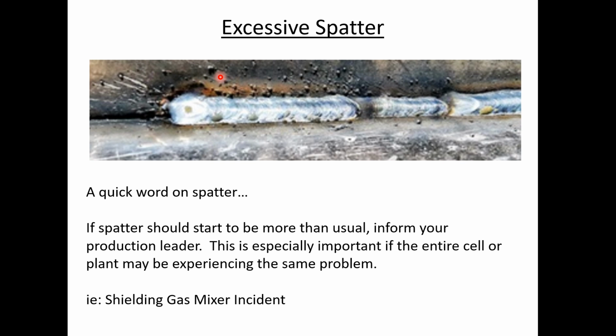So if there's any type of problem. Now, most nice, clean materials, if it happens to be non-coated steel, you should hardly have any spatter whatsoever. If you do have spatter, there's something else dreadfully wrong. Whether it's the gas or the choices or the electrode or filler metal, there's something else going on. So they don't like it because of that.